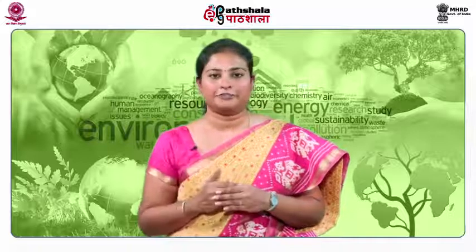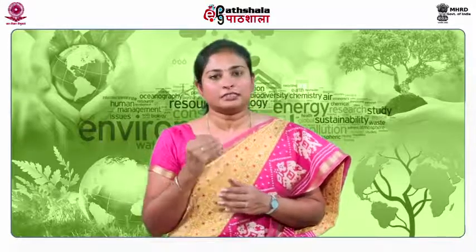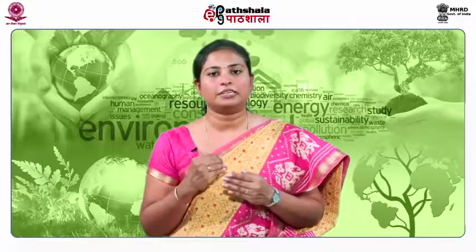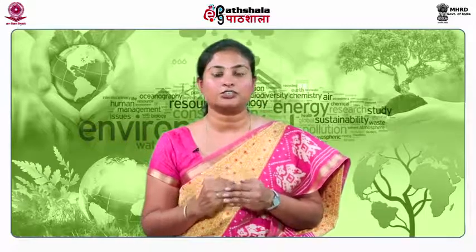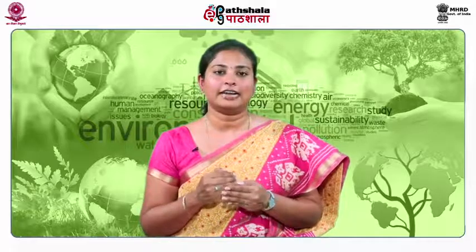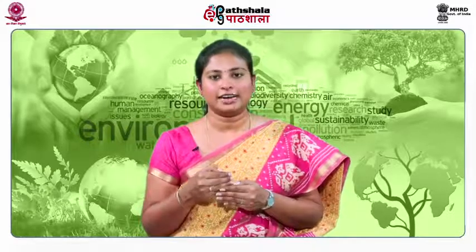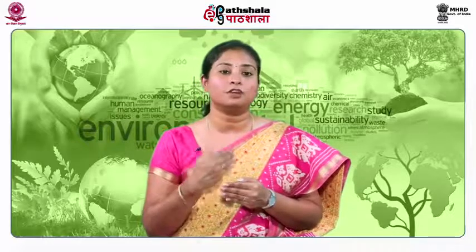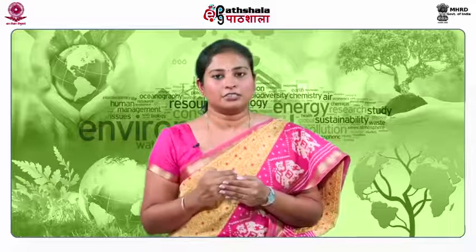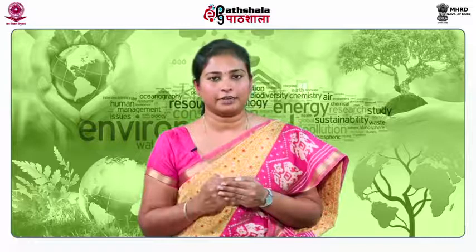The second type of landfill bioreactor is an anaerobic landfill bioreactor. The waste in the anaerobic landfill bioreactor generally undergoes anaerobic decomposition and results in the production of gases such as methane and carbon dioxide. They are generally referred to as landfill gases or LFGs. In an anaerobic landfill bioreactor, the gases are recovered and can be converted or used in the form of energy. Greenhouse gas emissions are also minimized during the operation of an anaerobic landfill bioreactor.